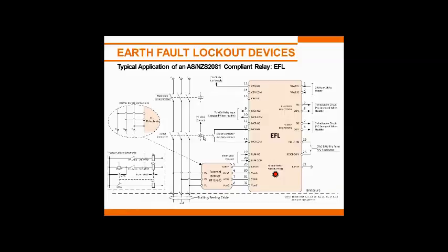Basically, the relay has to monitor what the main contactor is doing, and it does that through the auxiliary input contact. It also has an output for the main contactor to turn it on and off. There's also an output, because this is a frozen contactor function, that can head to a circuit breaker as well to get the power away from the main contactor. Yes, in the case of frozen contactor, there's also another input here called a run input, and we'll talk about that a little later on.